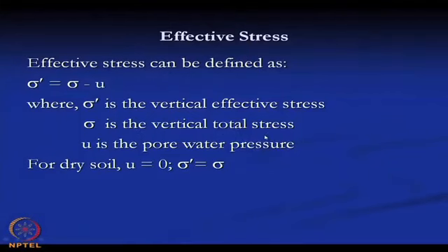If we now permit the water to flow, gradually the water will flow out, and the stress which was taken by the water initially will be transferred to the soil skeleton. As time progresses and the water goes out, the stresses are transferred to the soil skeleton, and the soil takes the stress in that fashion.